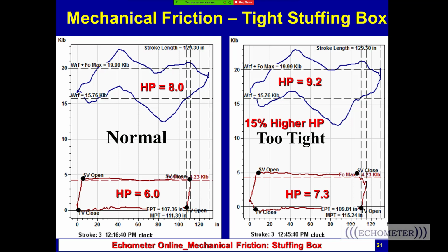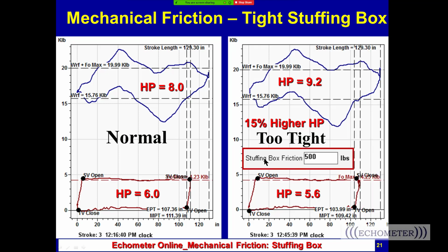And so the pump card is kind of like the trash can. Any forces that are applied anywhere from the surface of the dynamometer data down to the pump card, the wave equation assumes that the force is being applied at the pump, typically. So we modified the TAM software to add in a stuffing box friction force if you want. And so when you add the stuffing box friction force of 500 pounds, now the pump card looks correct, and the surface card is still too large.